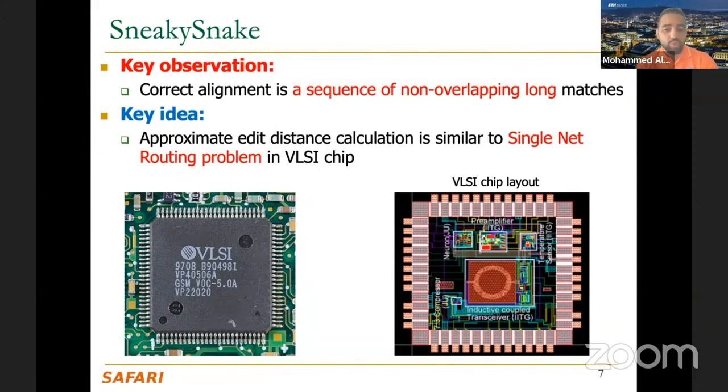Now, shortest path or lowest cost has multiple definitions. It could be the lowest latency, the minimum energy consumption, or the least routing cost, for example, because for these routing paths, you pay cost for them, right? And you don't want to increase their number because they're going to increase the energy or take space because they will collide with those modules. So your goal is to find the shortest path from one point to another point while connecting some of these components or avoiding these components. It depends on your design schema. So that is the single net routing problem.